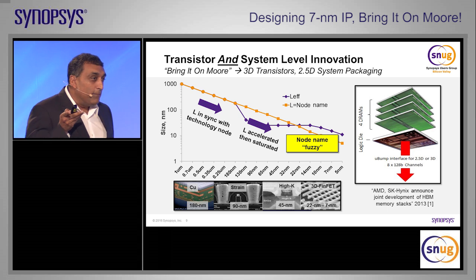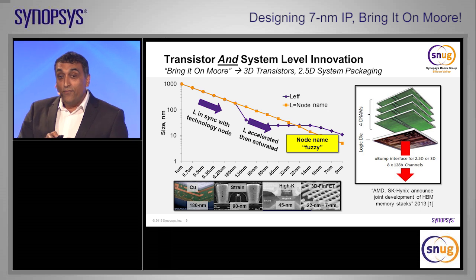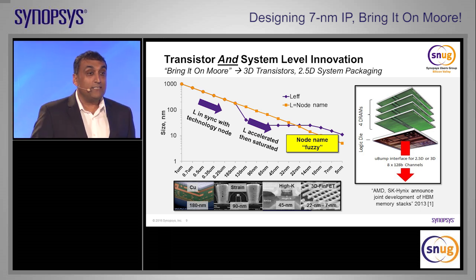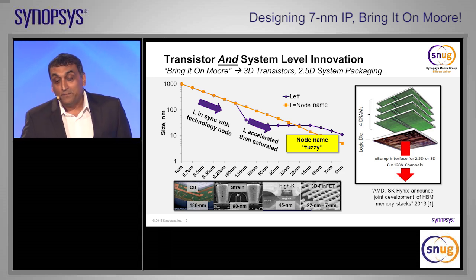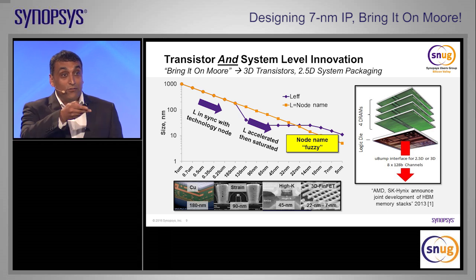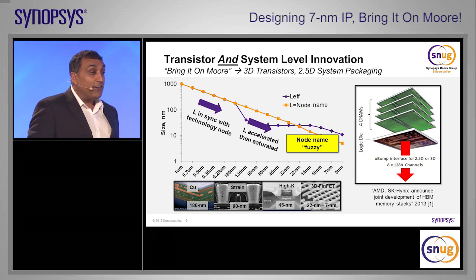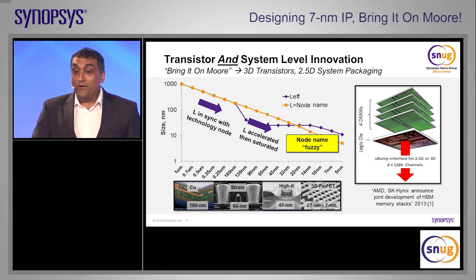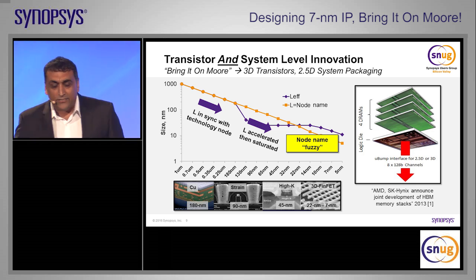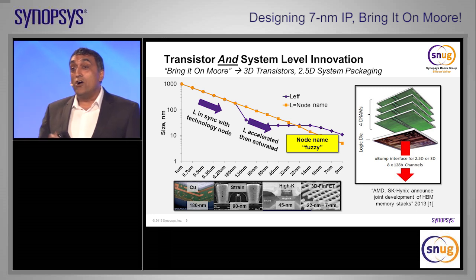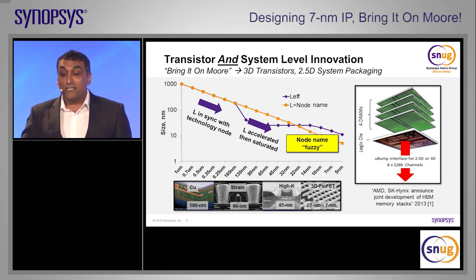This is a very interesting point to consider. At this time, in the market, there was a move to the fabless semiconductor industry, right? So you had fabs coming up. You had fabless companies starting. These fabs wanted to attract those engineers to that fab. So it became a marketing exercise to describe which technology node you're working in. So L accelerated and then saturated, and now, today, when we talk about 22 nanometers or 14 nanometers or 10 nanometers or 7 nanometers, it has no representation of the effective channel length. In fact, if you look at the purple line, they all look the same.